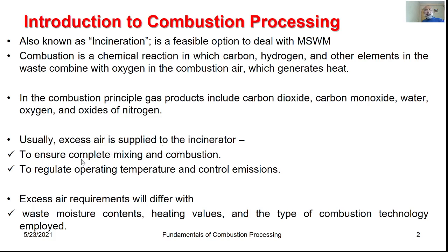This is to ensure complete mixing as well as complete combustion, and also to regulate operating temperature and control emissions. However, the air requirements will differ with the moisture present in the solid waste, the heating values of the waste that we wish to dispose, the kind of technique adopted for the combustion, and such factors.